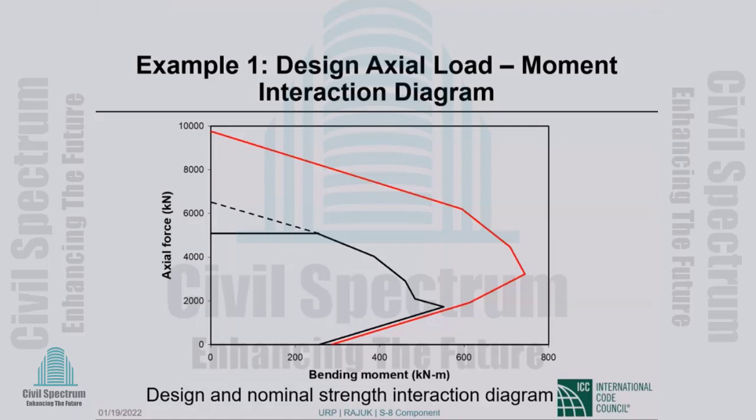Remaining column capacity would make sense if there is just spalling. You probably will forget about the cover concrete. Theoretically, you should figure out the strength of the reinforcement in place by taking some coupons or something.